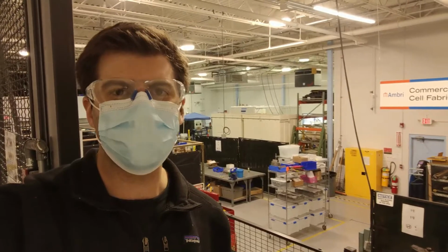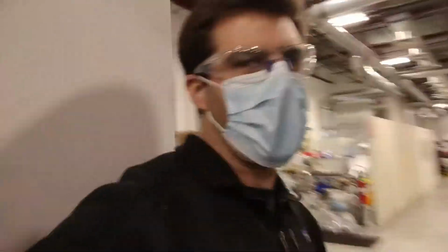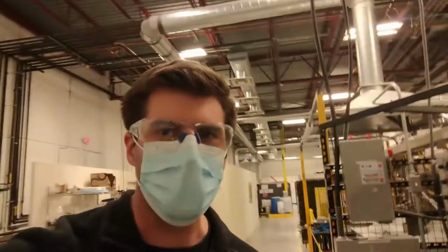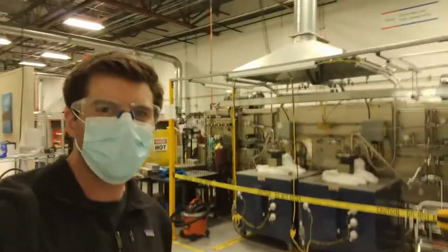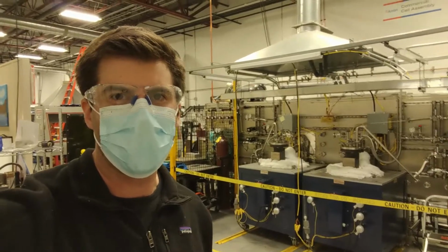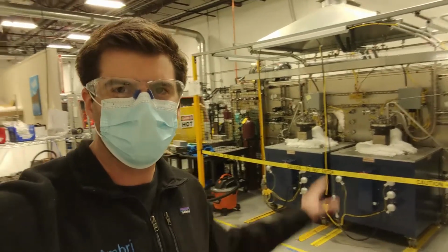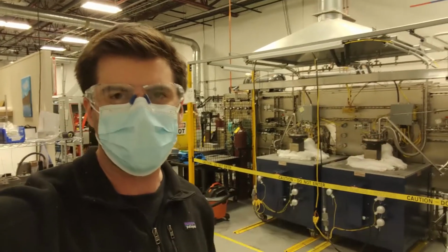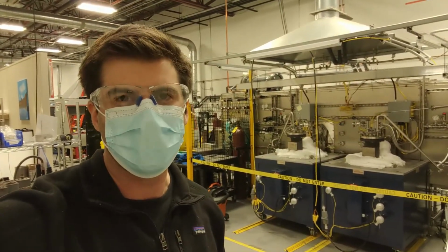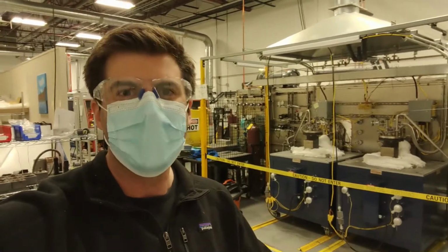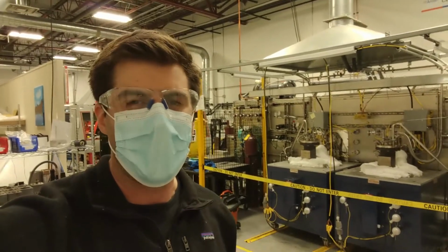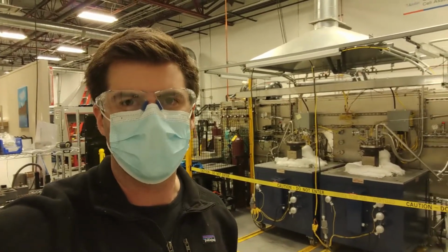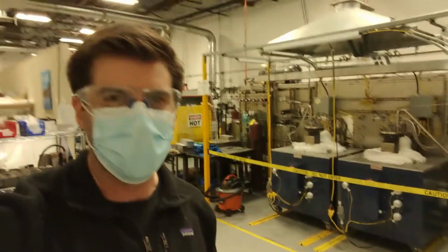Now that we've seen the cell fabrication area, I want to walk you over to the cell assembly area, which is where we load the active materials into the cell, melt the salt, and pour it into the cells. So this unit behind me is that cell assembly system. The 2 large blue boxes there are large furnaces, and the metal portions or flange assemblies sticking up out of the top are the salt melt vessels into which we pour the powdered salt. Then we heat that salt under vacuum, under air conditions, and melt the salt and have it ready to pour into the cells. Next we'll take a look at how the cells are assembled on the other side of the system.